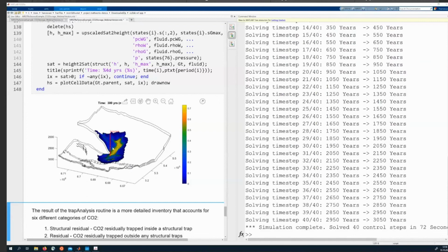So there are also tools for looking at optimizing the injection well placement to try and limit the pressure buildup as well. It's highly dependent on the reservoir, but that's why you do this simulation, to see where you want to inject, how fast you want to inject, what pressure you're allowed to reach. Does that help? Yeah, that's very good. Thank you.